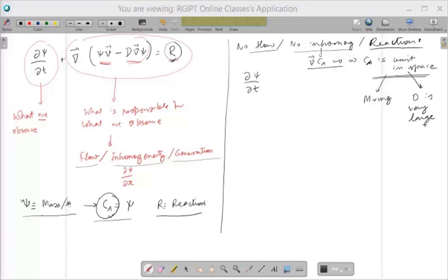Remember, diffusivity is a property of the medium. Diffusivity is basically the tendency to homogenize any concentration gradient. So if the diffusivity is large in a medium, then the medium cannot sustain a concentration gradient. Imagine putting a small speck of ink on a blotting paper. It quickly spreads out and becomes homogeneous in the region where it has spread.